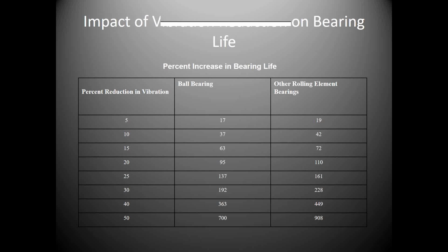But again, if we balance an electric motor, or even when you send the motor in for rebuild, one of your specifications to the motor rebuild shop is, I want the rotor balanced to 0.05 inches per second or less. And they can do that. The equipment's at the motor shop to do that. Most of the time they don't do it. Most of the time they don't even check it because we don't ask for it. But if you do that balance standard, your bearings in your electric motor are going to last this percentage longer.